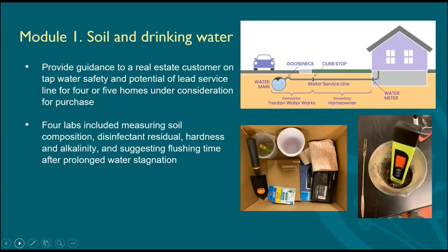Then for the second lab session, they had to characterize the water distribution in the pipes in their houses. They had to measure the length, what is the volume from the heater to the tap, and how long it would take to get a sample from the distribution system. So that was a kind of preparation for the third laboratory, in which they measured the chlorine concentration, and we worked on the kinetics of chlorine dissipation over time.